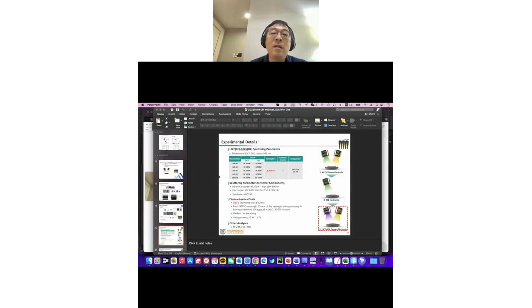Before we tried this, we didn't know whether this method would work, because after transferring from the target to the substrate using atomization and plasma, the LSCF is redeposited. But by controlling the RF sputtering power, we could transfer this perovskite structure from the target to the substrate.